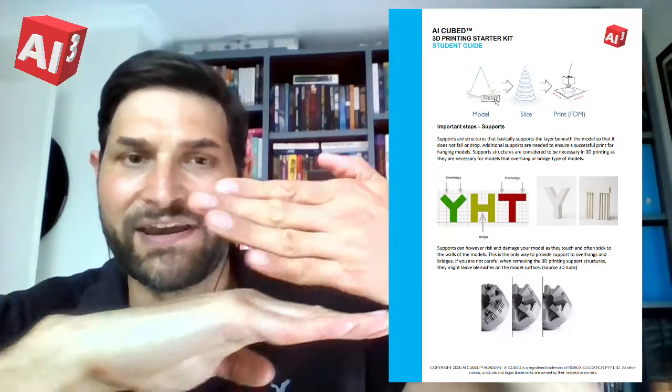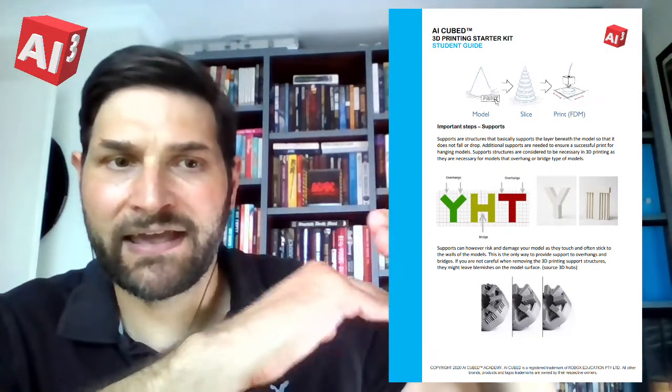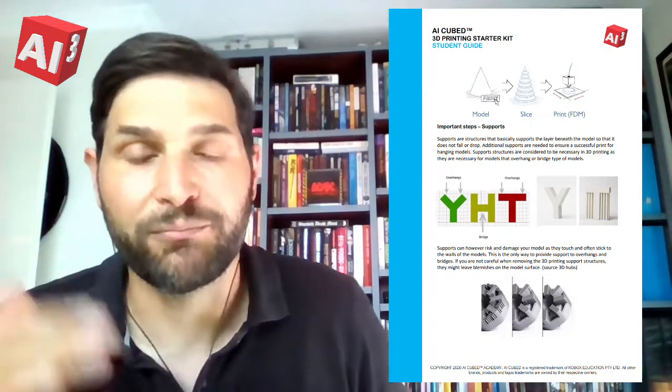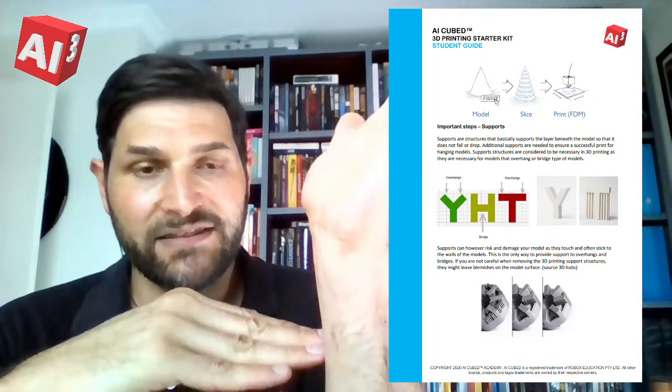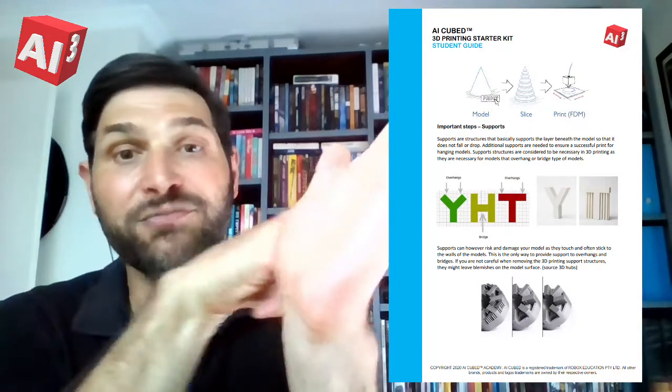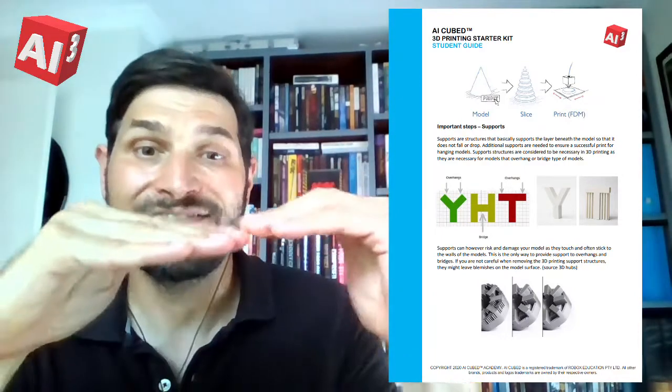If we print something on an angle, it may fail and fall over, or the printing head might not be able to print the lines very fine. So that's important. If we do have something that's going to overhang, like in our example here, you can see we've got three letters, Y, H, and T. They're all formed slightly differently, but on the Y, if we were starting at the bottom printing up, we would start to print some overhang. And then on the T, we would definitely have overhang.